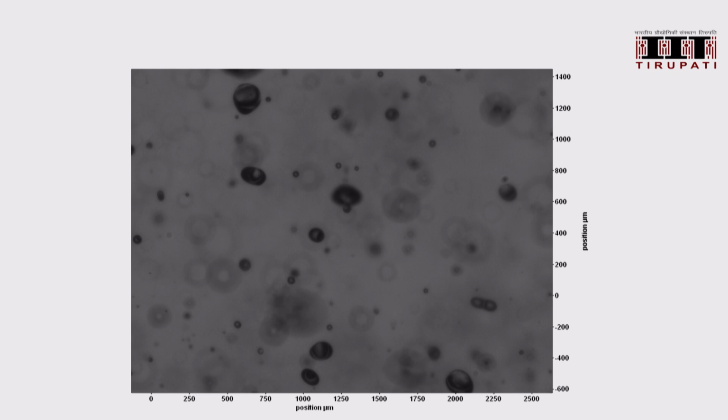Now you can use MATLAB algorithms, if not the commercial software, to find the total pixel area of, let's say, this drop. From that, we can get the size of the drop. Again, even if the drop is slightly non-spherical, we are equating the area and getting the size. And if this drop is distorted in the other direction, we will not get that information. So you have to keep that in mind.